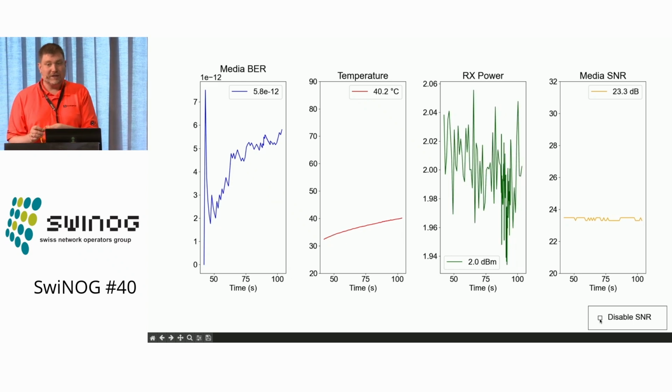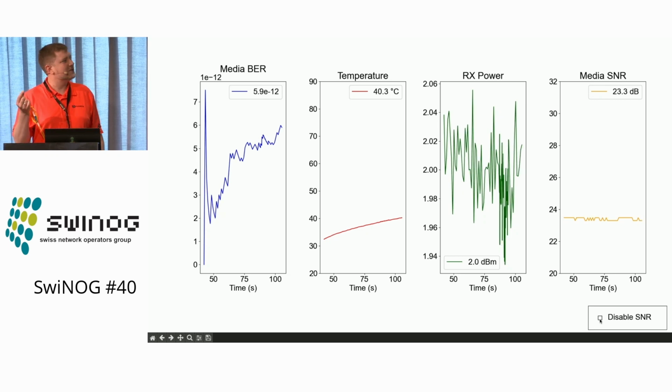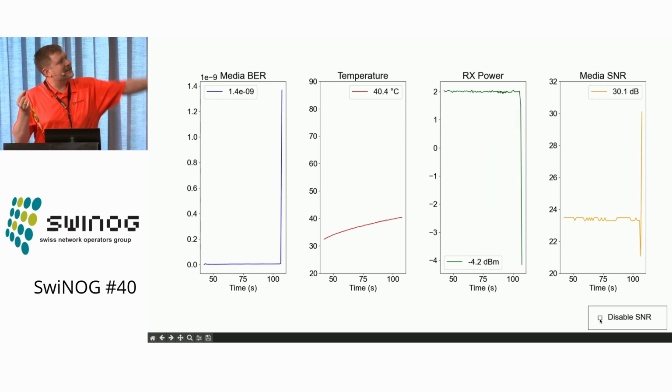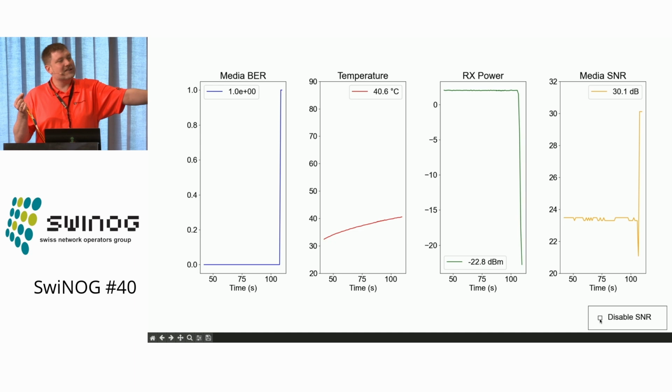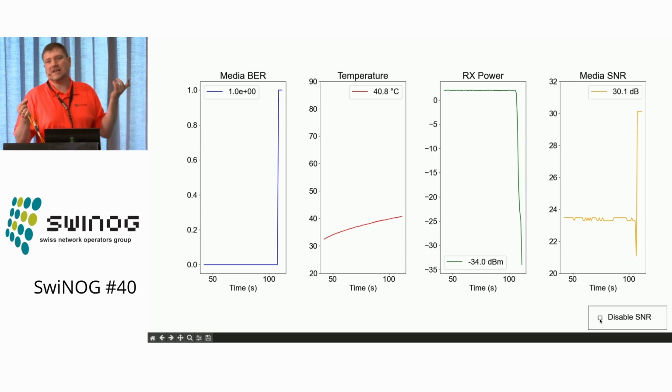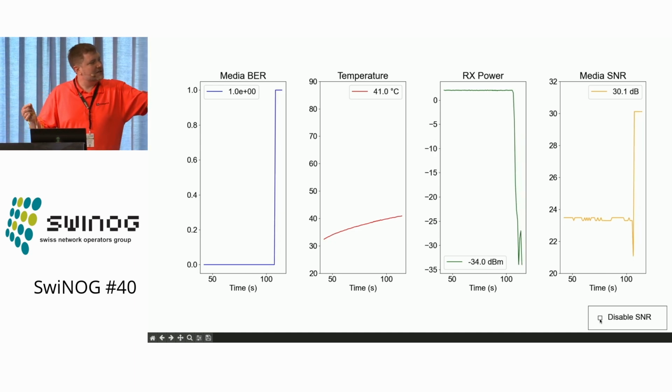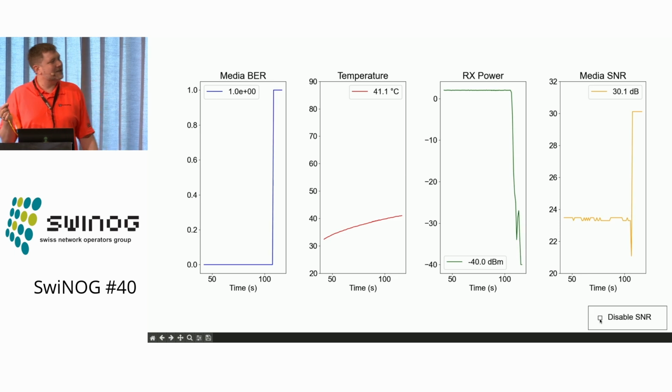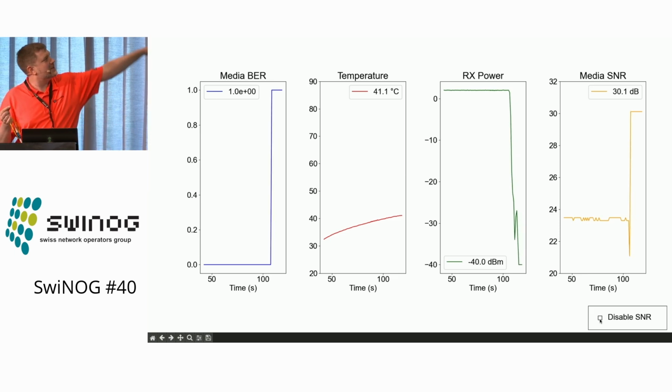And to really prove it's not a pre-recorded video, I'm going to bend the cable like this, and it's auto-scaling itself. And the lowest point, you might have seen our application or any other OPM, the lowest value is usually 40. Here we go. Now we are out of signal, and the bit error rate goes to 1.